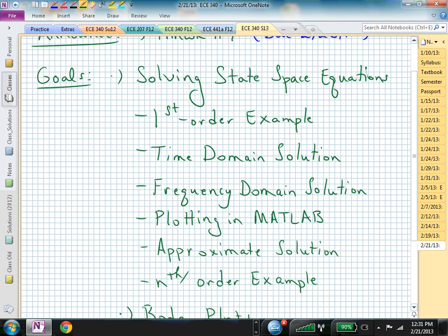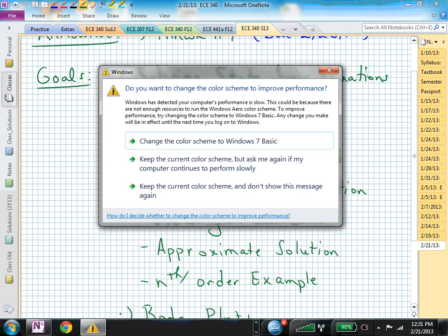We'll examine what we might need to do if we're going to sketch that waveform or that result in MATLAB. How do we create that, or what do we need to pick? And again, it's those two questions. How long do you simulate, and how fine do you chop up the time axis to make that simulation happen?